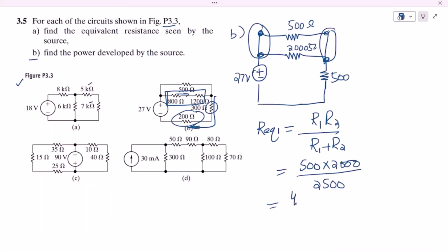So this is now 400 ohm, and you can see that in parallel the dominant resistance is the lowest one, while in a series circuit the dominant one is the highest one, because it dominates in the equivalent value. So you can see that this is 400, which is closer to this lower one, and in series you would have seen that this is 2000, which is closer to the highest one. Therefore in series the highest resistance dominates, while in the parallel circuit the lowest one dominates.